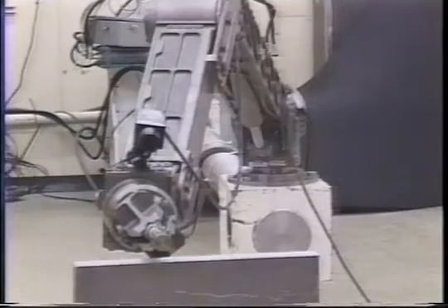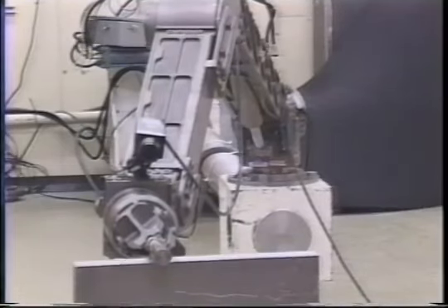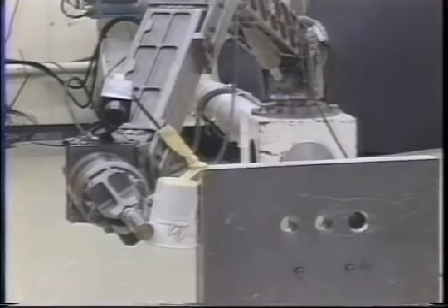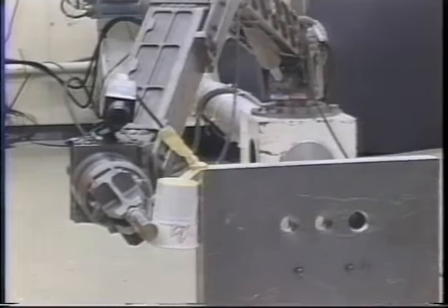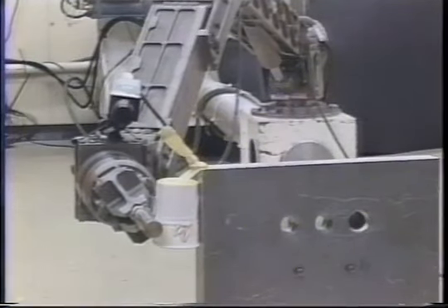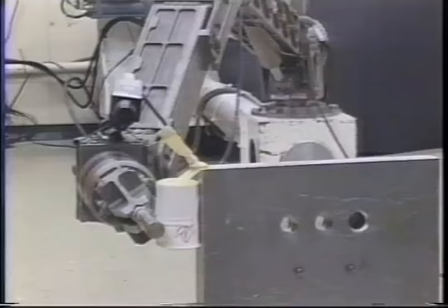Again, with inertial force active damping control, the manipulator can make a smooth transition to a contact without chattering by dissipating impact energy. To demonstrate that the contact force is being regulated, a paper cup was used. Using the force-torque sensor at the wrist, a small force in the horizontal direction is controlled. And as we can see, the cup is not dropping or being crushed.